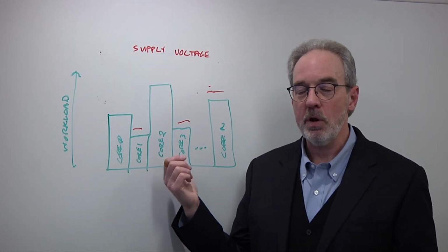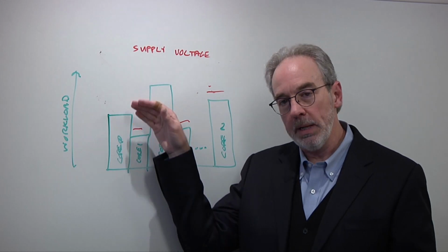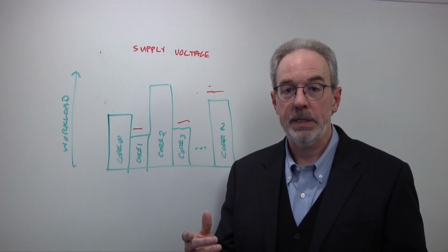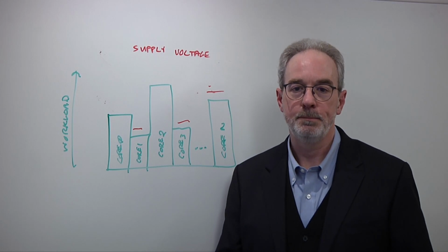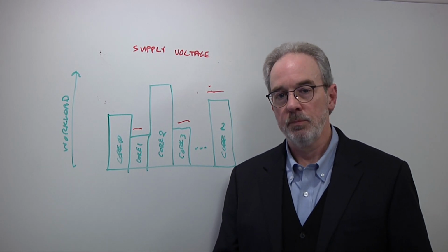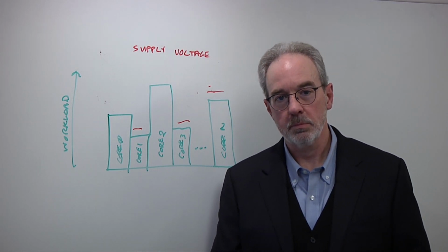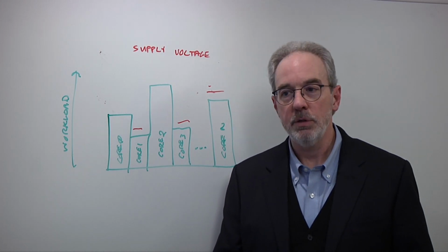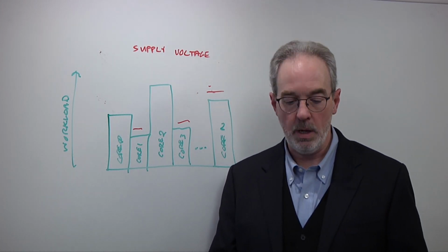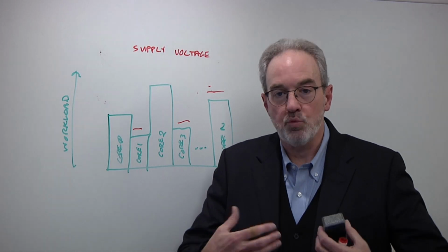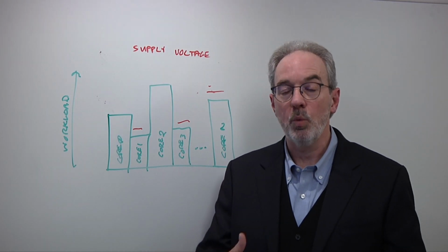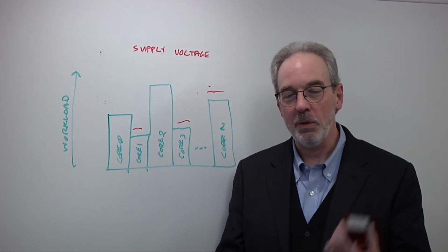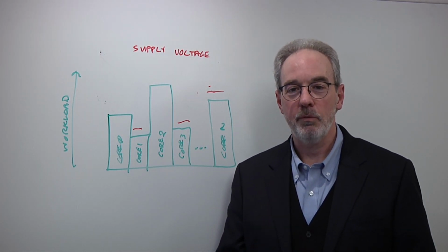The other thing that I haven't drawn here is that the more quickly you can manipulate the voltage up and down, the more rapidly you can go in and out of these power states, and the more power savings can be had. How do you get that feedback to know exactly what's happening on each one of these cores and what you need to manipulate in terms of the voltage? Well, that's a challenge. I think we've seen in the industry over the past few years a drive towards more of a world where we're sensing what's happening. You know, you wouldn't build an oven without a little window on it. You wouldn't back up without looking in your rearview mirror.